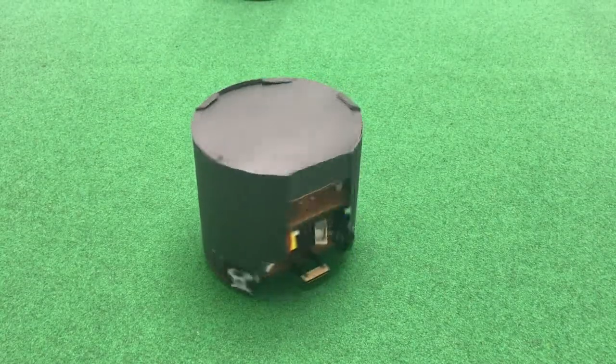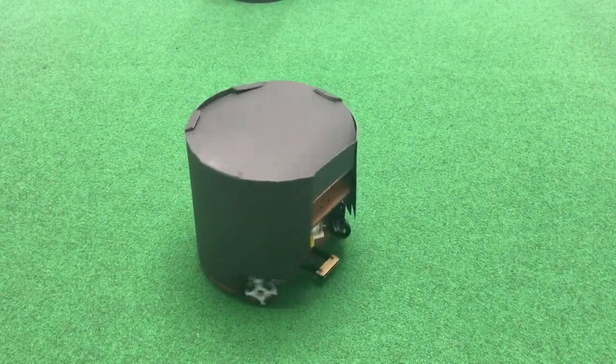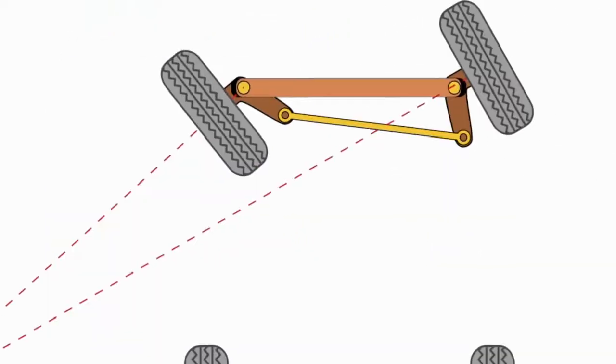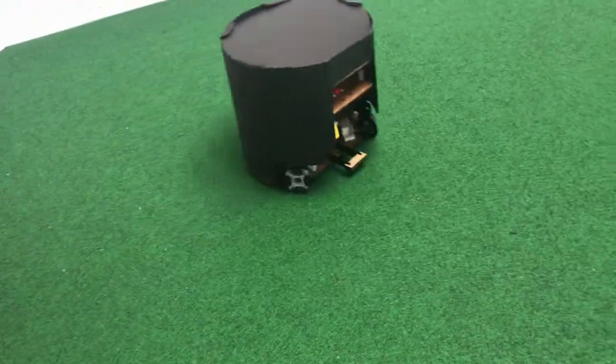I designed an omnidirectional drive system. This provided an additional degree of freedom as opposed to the differential drive and Ackermann steer. This allowed the robot to translate and rotate simultaneously for efficient movement.